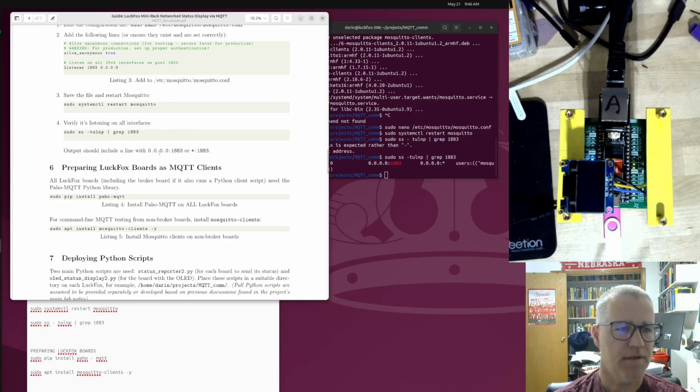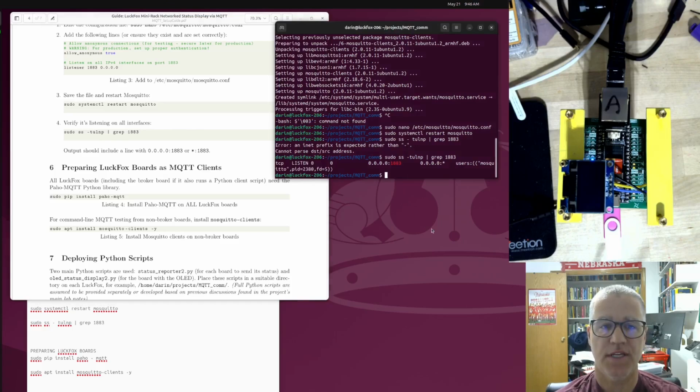Okay. So the broker is set up here now. So now we want to prepare all the other boards as a client. As I mentioned, we're not going to do every board in this video. You would just do this for those boards, but we'll do that now on this board. So the first thing we need is to install this Python package, Paho. So we'll go sudo pip install paho-mqtt.